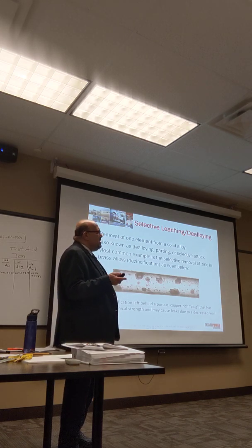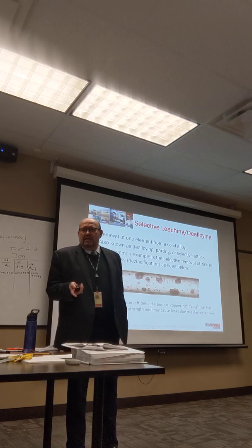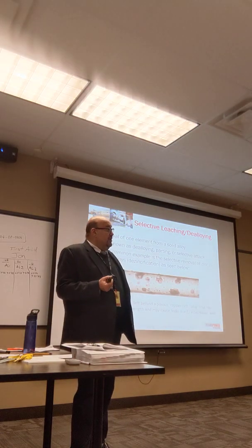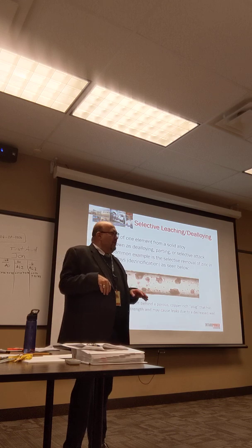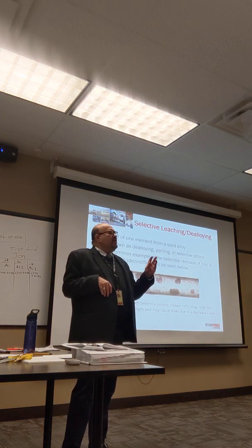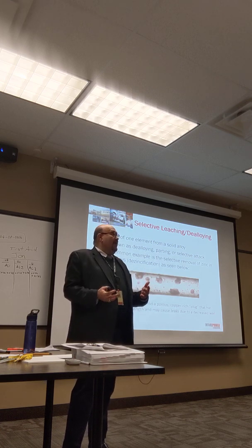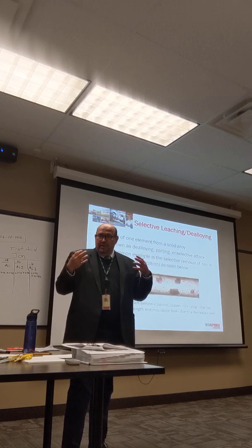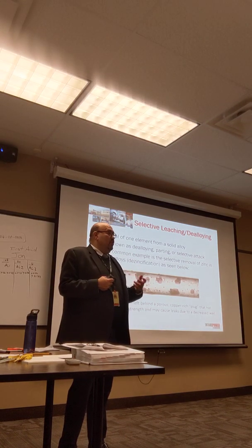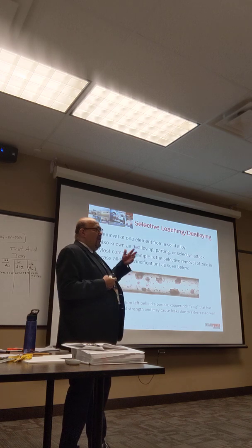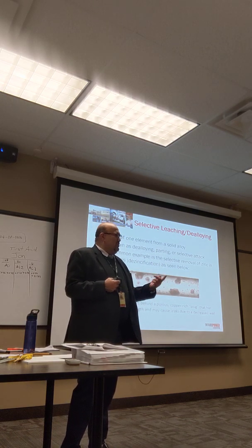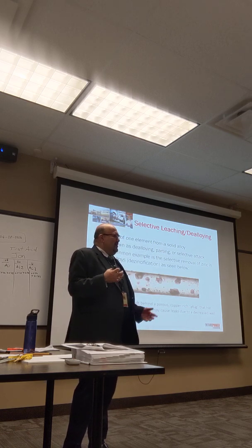And I think in the boilers, it's nickel and nickel copper. Yeah. And the copper was going at a higher rate, so you are left with a sponge-like material. It's not really sponge-like, but it's getting there, and that's why we're doing all the inspections, to make sure that we don't leave it until your boiler is just leaking. You can't change the tubes. You cannot retube the boiler. It'd be easier to throw it away.